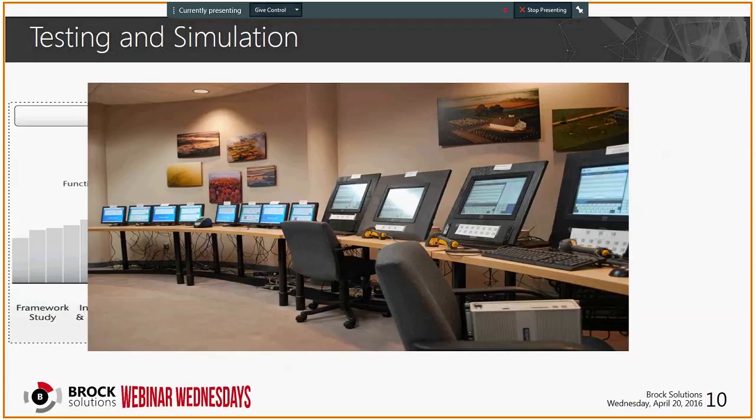As an example, you might want to simulate ERP creating an order and sending that down to MES. Your MES system can process the order and start the execution of that order, and maybe that involves sending recipes down to the controls layer. Then you can simulate the controls layer actually doing something and sending back information to MES, like material consumptions, inventory moves, things like that. MES will then grab that message from the controls layer, aggregate the data, and send the necessary information back to ERP. So you can actually do the whole flow of how your system is going to work in this simulated environment.